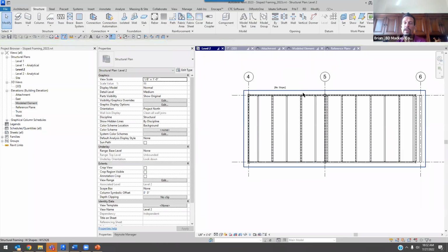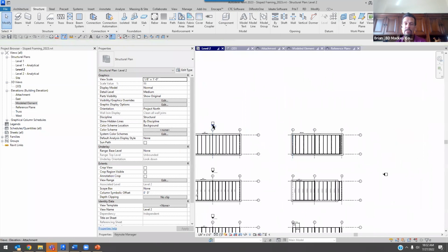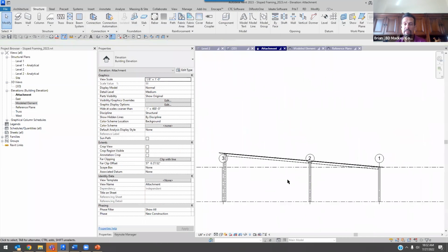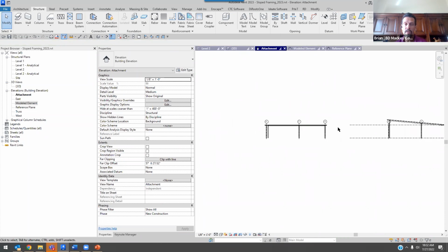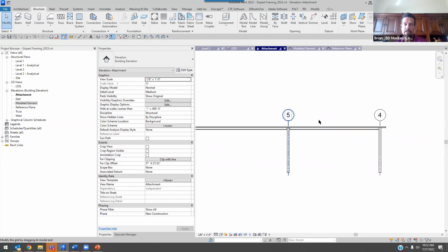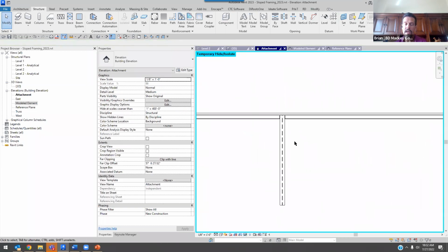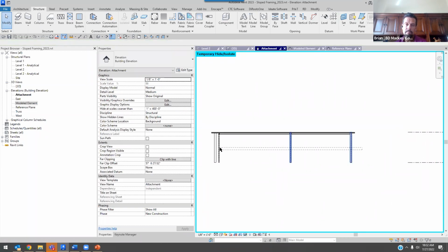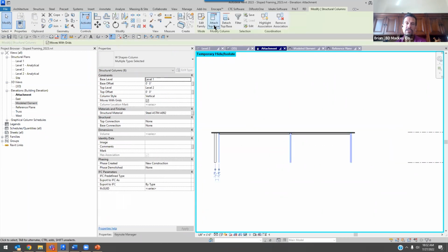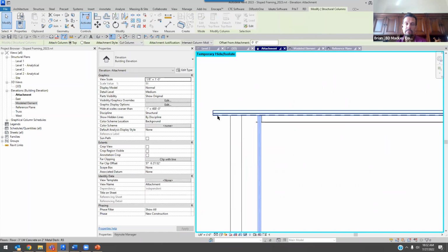All right. Now here's the beauty of this. If I go into now the elevation view where I've got this set up over here, I'm going to hide grids again with my sunglasses. I can take all of these columns and attach them to this roof, right? Again, you can do the cut column, midsection, max intersection, all those same options are still there, but I can attach those to that roof.